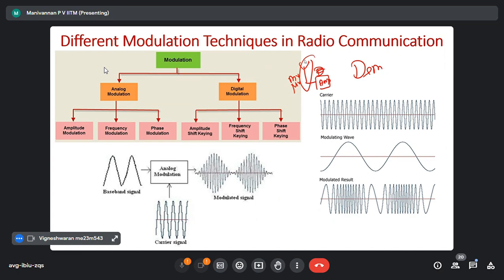Few centimeters. I told you the signal amplitude depends on the length of the antenna. Your antenna over your car is only 1 meter, half meter, 1 foot. In your cell phone, a few centimeters. So the picked signal will be a few microvolts. That will be amplified by what they call a pre-amplifier. From microvolts, it is amplified to millivolts. Again, there will be one more amplifier, a power amplifier. Correct? That will amplify to volts, maybe 10 to 100 volts.